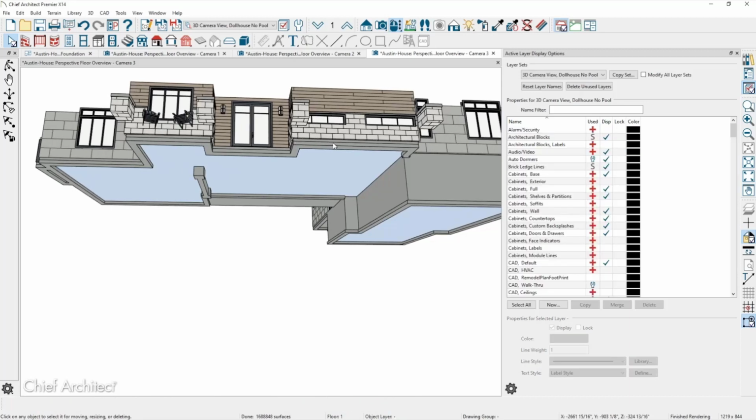Yeah. Well, usually I'd have to take a look at it. Usually what I would do in the room definition is set that to be a porch and build it. When you build your foundation, if it's set to be a porch, it'll come in at the same elevation as the rest of your slab. Well, unless you lower it. And I've done that. I just didn't, in this case, want a footing out where these columns were because it wasn't necessary, because that's what's going to carry the load of the roof.